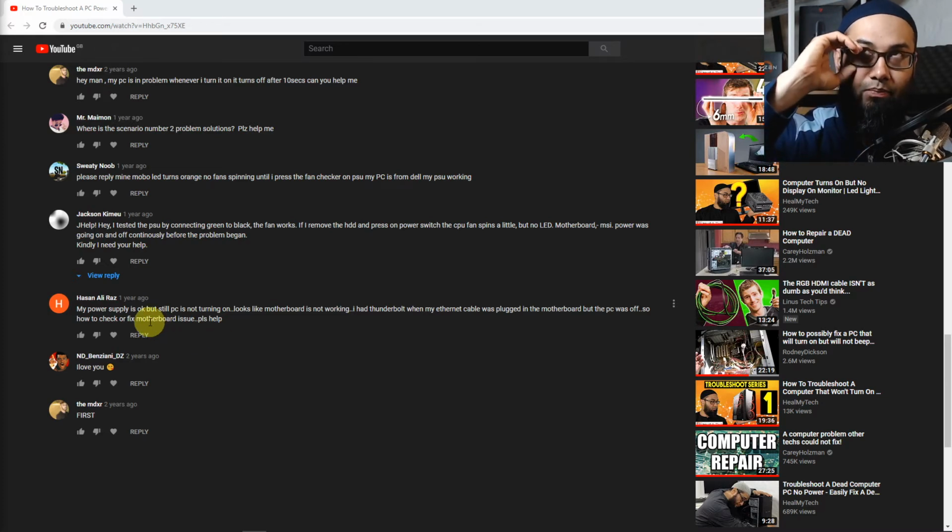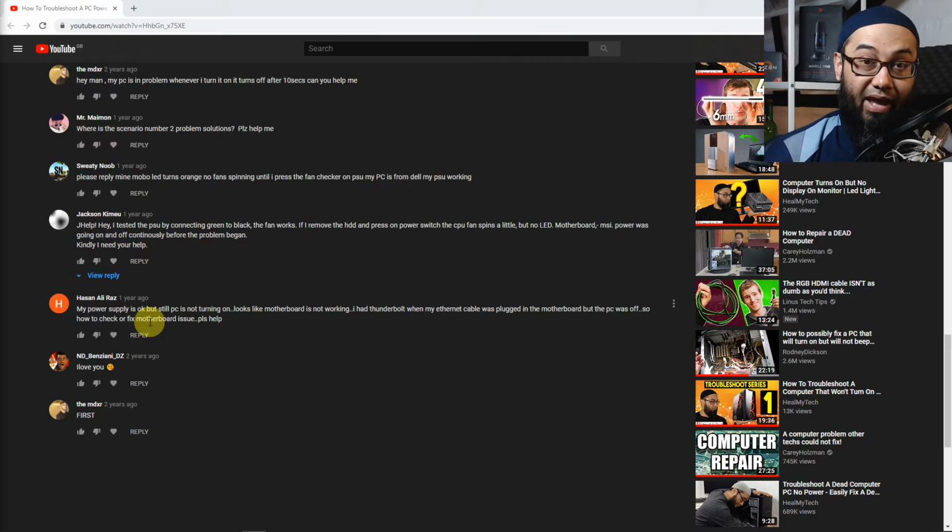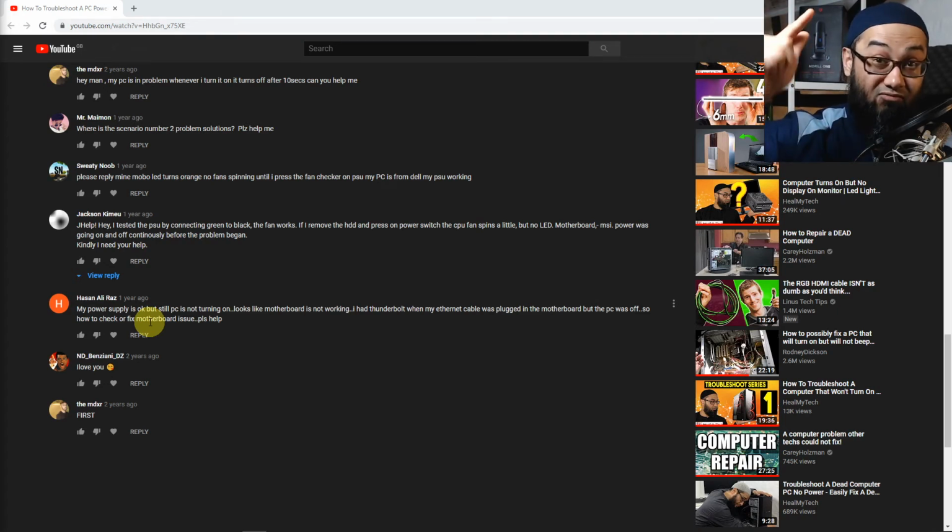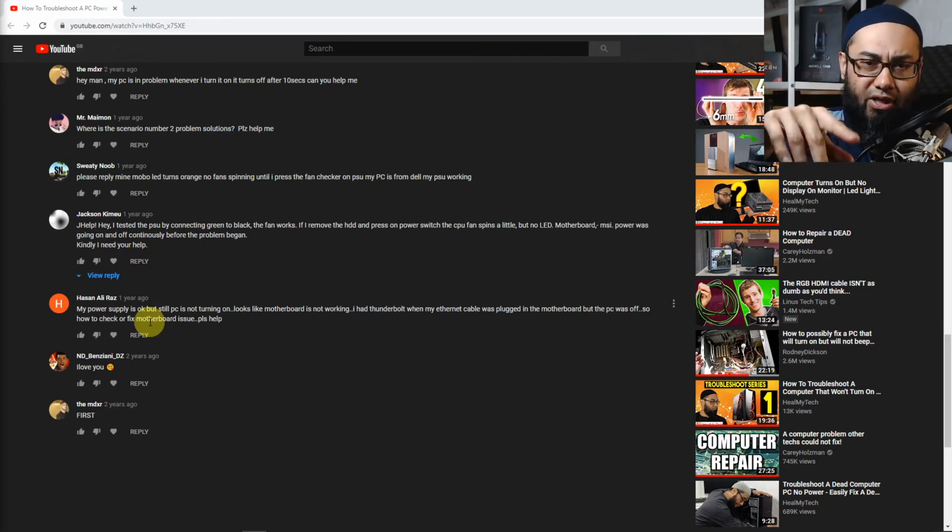All right. So Hassan Ali, the motherboard test is number 4 of our Troubleshoot series, part 4. You'll find the link in the description for that. But again, before you can come to the motherboard test, you have to eliminate the power supply, because you're saying again it's okay, but how, unless you've taken this power supply and put it in a different system to test it there. You have to eliminate power supply, processor, even RAM, and then you can do the motherboard test. Maybe the motherboard test is part 5, I'm not sure. Check the description below. But just to answer you very briefly, you have to test one thing at a time.